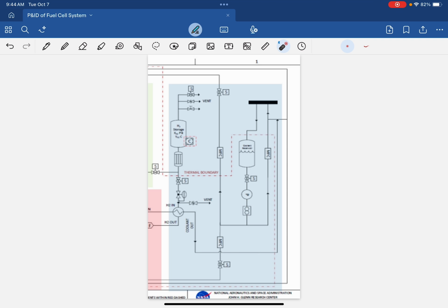And then right here is a turbine flow meter. So what this is going to do is measure the volumetric flow rate. And the reason for doing that is to make sure that we have a certain amount of power going into this pump to make the volumetric flow rate at a certain point. And so these two kind of work intertwined with each other.